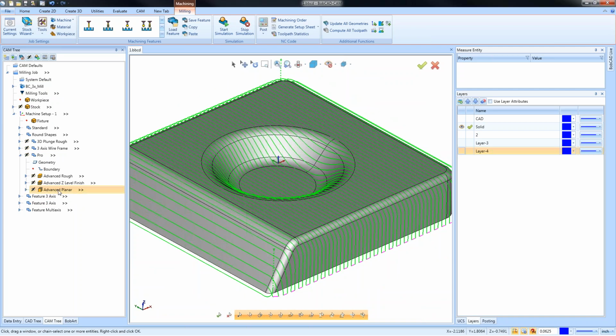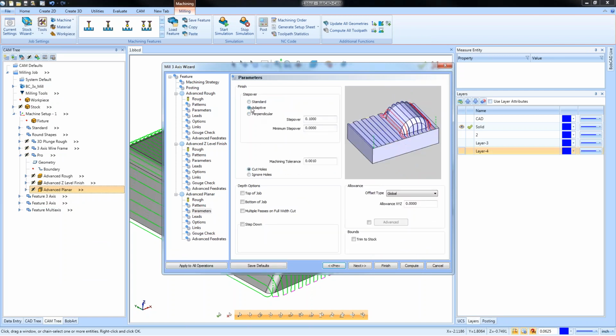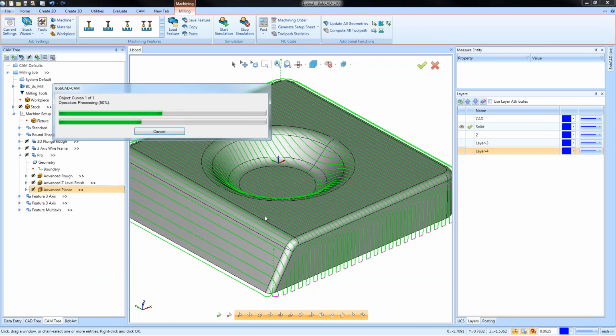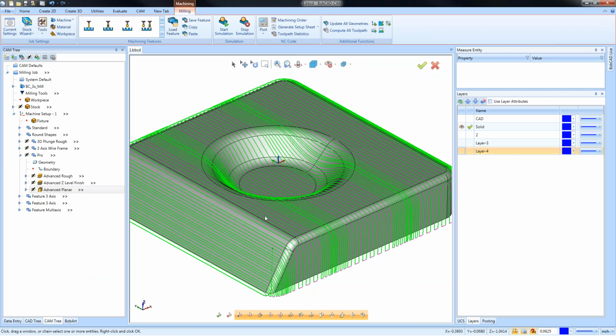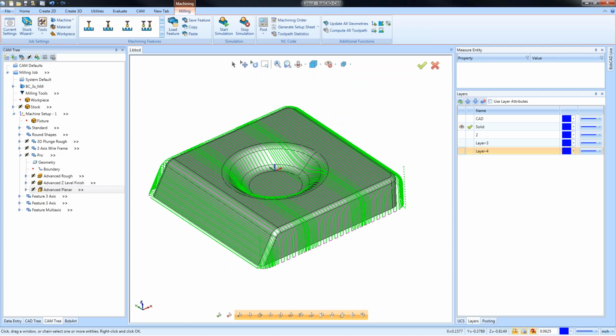So what can you do to adjust that? Well, in the Pro toolpaths, you're going to have more options, and one of them is this adaptive step over. With the adaptive step over, wherever the steeper areas of the part are, it's going to take additional passes in order to give you a more consistent finish.